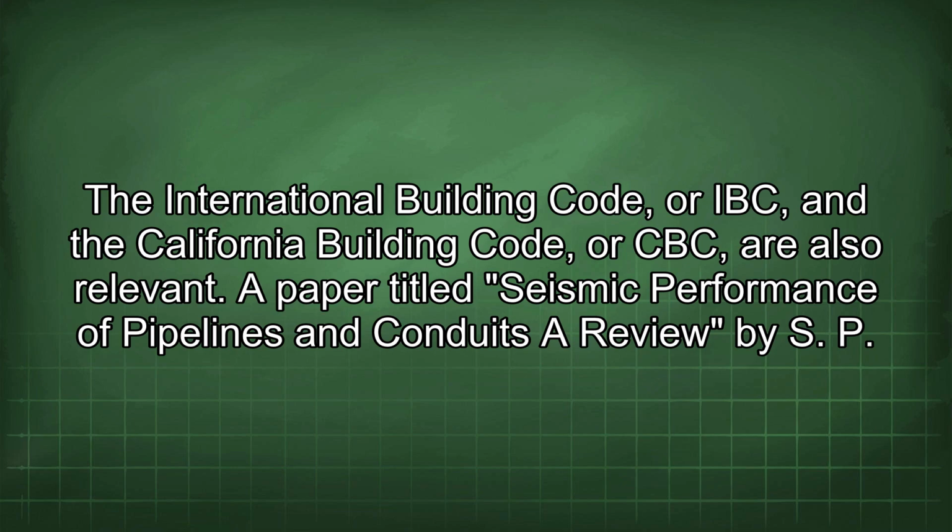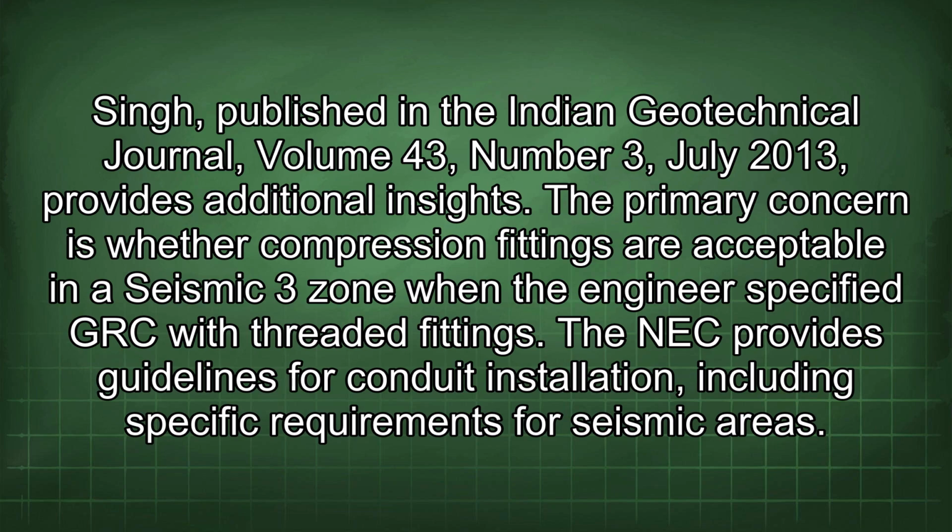A paper titled Seismic Performance of Pipelines and Conduits, a review by S.P. Singh, published in the Indian Geotechnical Journal, Volume 43, Number 3, July 2013, provides additional insights. The primary concern is whether compression fittings are acceptable in the seismic 3 zone when the engineer specified GRC with threaded fittings. The NEC provides guidelines for conduit installation, including specific requirements for seismic areas.